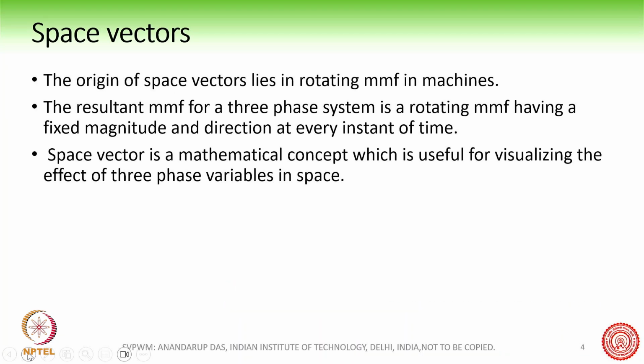So at first we will understand what space vectors are. The origin of the space vector concept lies with the rotating MMF in machines. In the rotating MMF concept, we express the resultant MMF of three-phase quantities by a rotating MMF. For example, if you have a balanced three-phase sinusoidal supply given to the stator winding of a three-phase induction motor, then the resultant MMF produced is rotating in space.